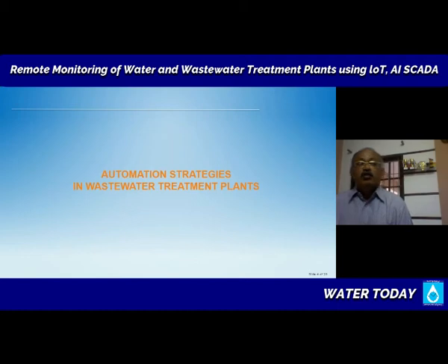Other than that, what do you want to monitor at the STP inlet? Do I want to know the biological oxygen demand or some other nitrates and other metals and things like that? That is a call that needs to be taken specifically for your plant, not generally.